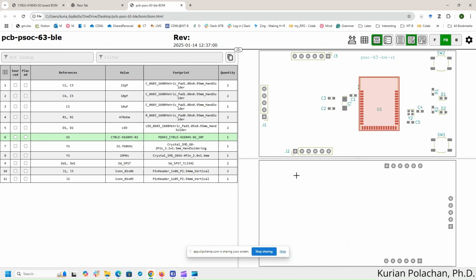Yeah, so that completes the PCB design tutorial. You have learned how to create a KiCad project, how to create a schematic, how to do an error checking of the schematic, how to create a layout, how to do a design rule check of the layout, how to pour copper at the bottom and the top of a PCB and connect it to a ground net, how to generate Gerber, and how to generate the bill of the material.